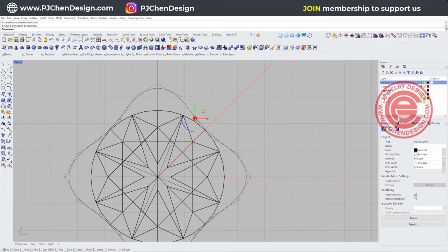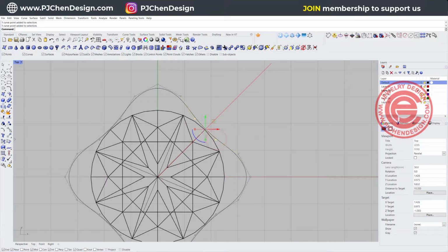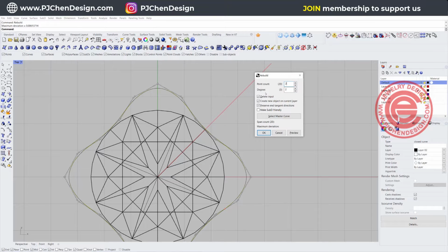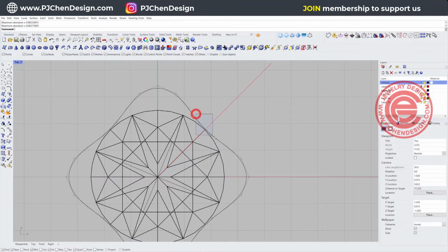So when you are moving those 2 points, we want to use the Move tool. I want to make sure my Near point is checked for my Alt snap, and I'm going to snap right here and just move it up along this guide. And I'm going to bump it up even more, to 24. We need to have a point in the center, so let's go to 28 there, so there will be one right in the middle. All right, so now we have this. I'm going to use the Move command, and then we're going to move up like that. So that's how we get this bump right there.